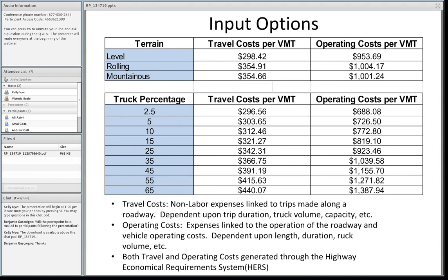So if it is a diversion, it is the additional time above and beyond what it would normally take you on the roadway without the work zone, that additional travel time on the diversion, the additional travel time that's associated with everyone exiting and detouring, and then the travel time that would be associated with the work zone, whether or not there was a diversion or a detour, anyone that needs to go through there, if there's a reduction in speed limit, there should be some travel time cost.